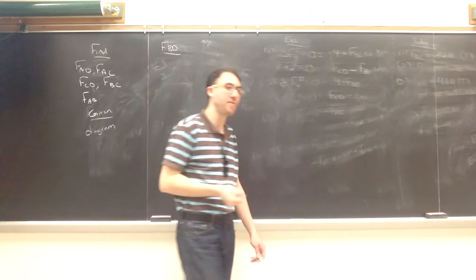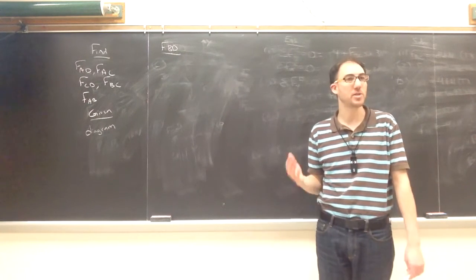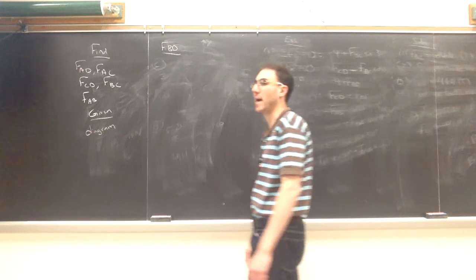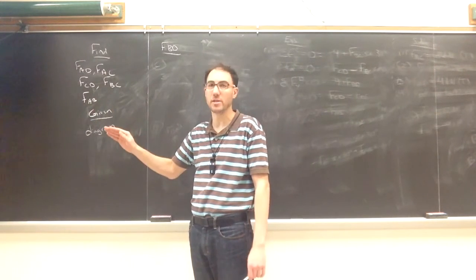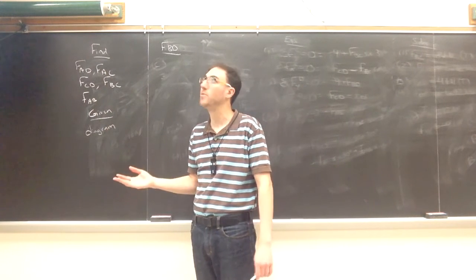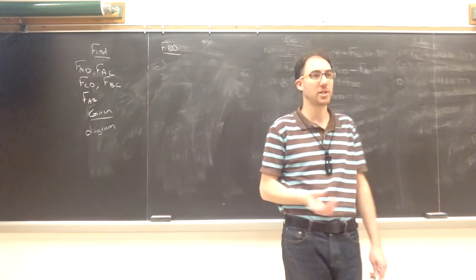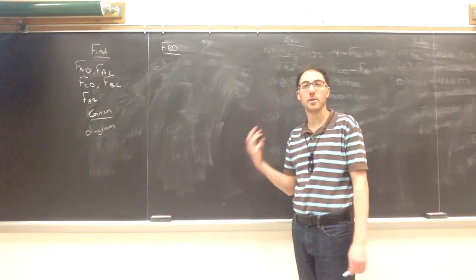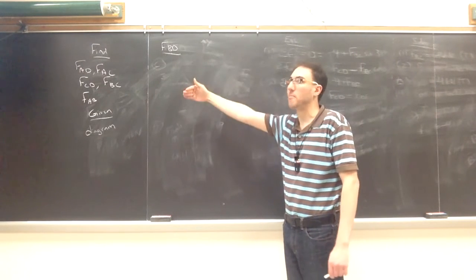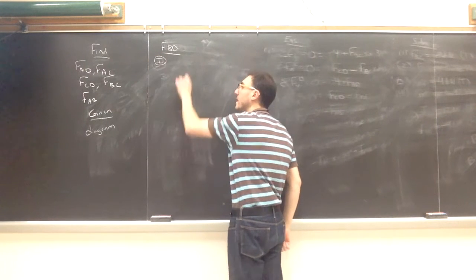If we have 3 or fewer external reactions, it's statically determinate, and I recommend starting with the external free body diagram in that case. Again, you could jump right to drawing pins if you wanted to, but I recommend it's usually best to start with that external picture. So again, A is a roller, B is a pin, 3 unknowns. That leads us in the process that I recommend drawing that external free body diagram in that case.